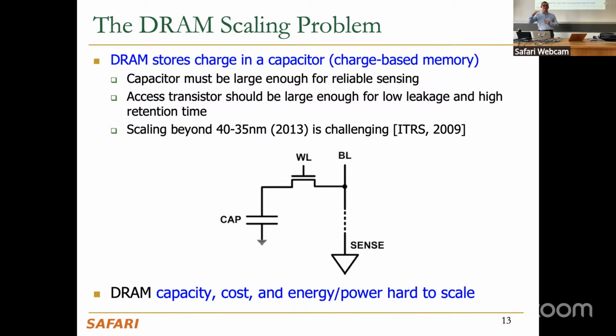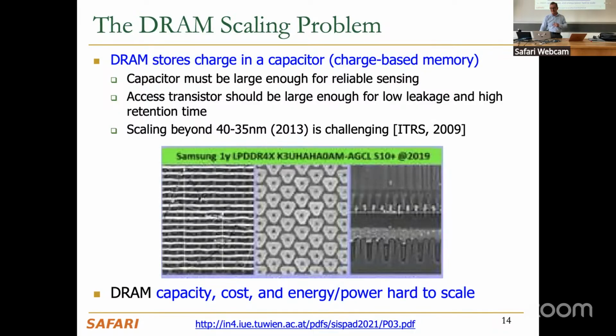There are also lower level explanations that we may get into when we talk about RowHammer, for example, device level explanations. But that's the high level thinking. Your capacitor, or your charge storage unit, size reduces, and the charge storage units become closer to each other. Also the interconnects become closer to each other. For example, this bit line becomes closer to another bit line. This word line, which is not exactly shown here, the word line that's controlling this access transistor, becomes closer to another word line. So there could be crosstalk across these interconnects, which also impacts reliability of operation. So that's in general the downside of scaling technology to smaller dimensions. You run into these noise effects that are hard to control and sometimes hard to understand also. And we'll see a lot of that when we talk about memory robustness. Does that sound good? Okay. Feel free to ask questions. As I said, the goal of this course is to think deeply and critically. Okay, this I've shown you.